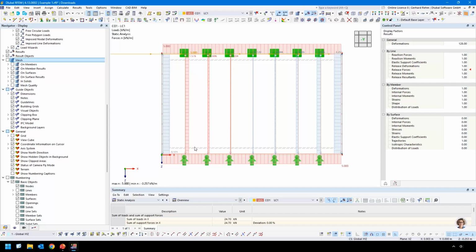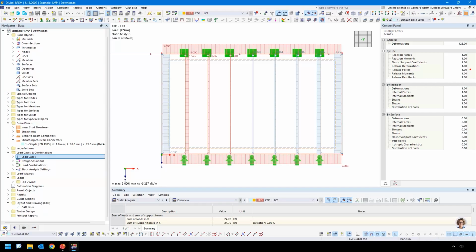shear walls, because we have used a single surface now for this shear wall. Sometimes we see Rfem 5 files, which use some line releases to simulate a timber shear wall, and there we see really often that it's modeled with one single surface, and of course this is not representing a correct shear wall, because a shear wall always consists of multiple sheathings.